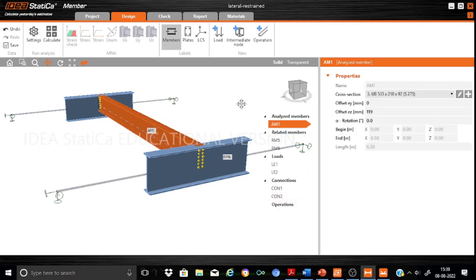What we mean by the operation here is, whenever we go for the detailed investigation, in many cases, suppose that I'm dealing with a plate girder, I may have to add some kind of a stiffener to improve what we call the web capacity, or to improve the shear buckling. In some cases I may have to add some openings coming through the girder.